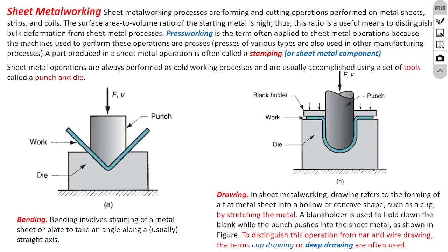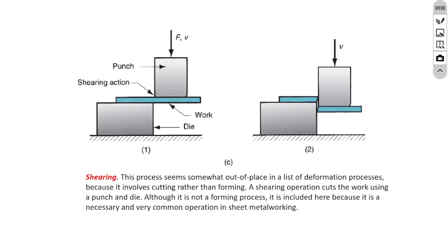They are gripped. We apply the deformation force and plastically deform the material. This technique is called deep drawing. The process is the deep drawing process. If it is necessary to cut the material, we use a shearing machine, shear cut, like scissors, and while applying the necessary force, we cut the material. It is the shearing process.